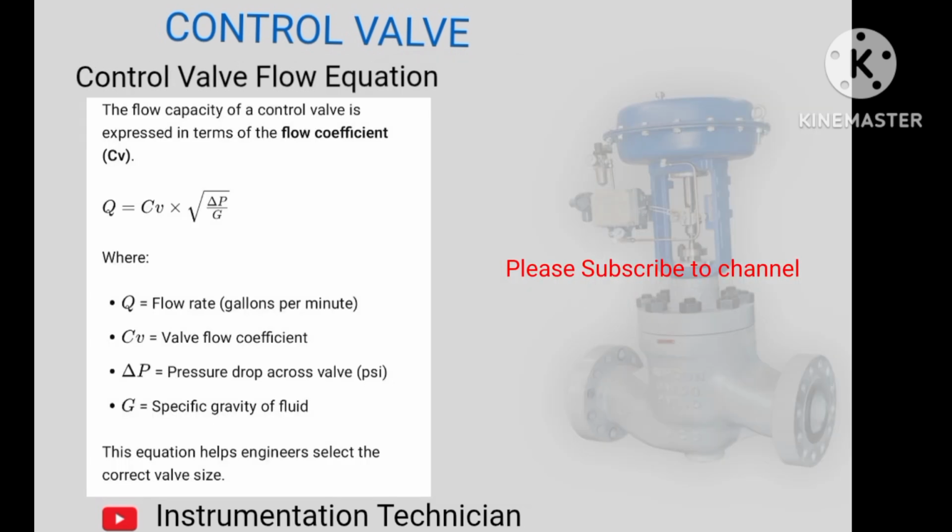Control valve flow equation. The flow capacity of a control valve is expressed in terms of the flow coefficient Cv, where Q equals flow rate in gallons per minute, Cv equals valve flow coefficient, ΔP equals pressure drop across the valve in psi, and G equals specific gravity of the fluid. This equation helps engineers select the correct valve size.